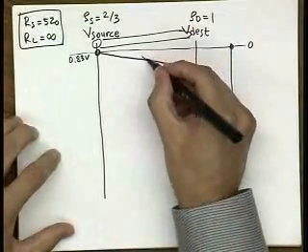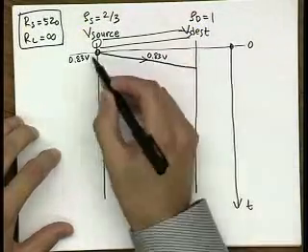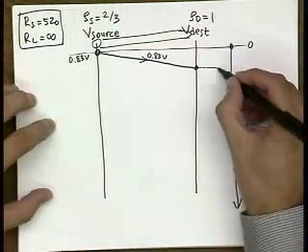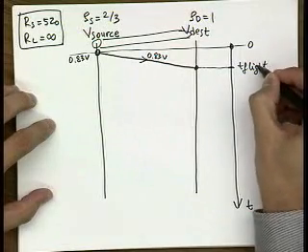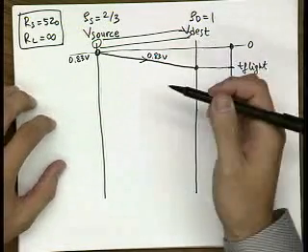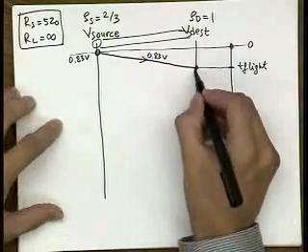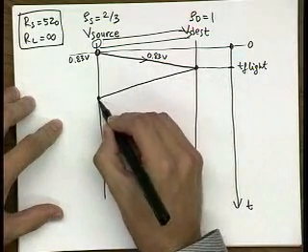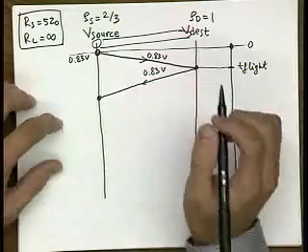And the incident wave is equal to that value that is injected into the line. After time of flight, T flight, at the source end you have reflection. So what this reflection coefficient of 1 means is that the reflected wave is equal to the incident wave. And then you have, again, 0.83 coming back.